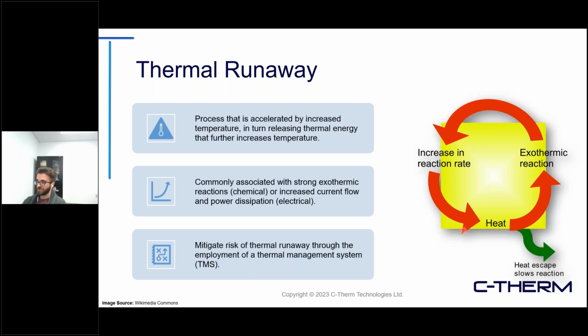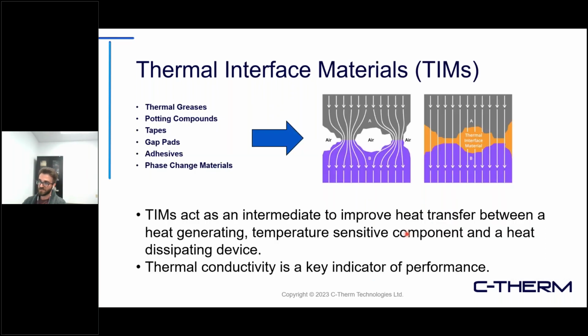Now, mitigation of thermal runaway is accomplished through a thermal management system. These can take many different forms here, but core to any thermal management system is the thermal interface material employed. The thermal interface material, or the TIM, that's involved plays a very significant role, because if you have heat traveling from your component, your electric or your heating component, to that thermal management system, which could be an active, hybrid, or passive system, pulling that heat away, there's going to be this joint that occurs.